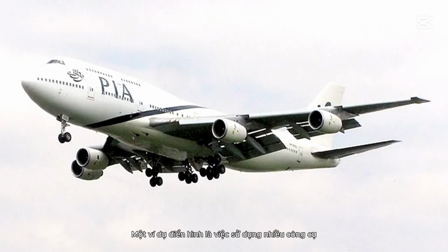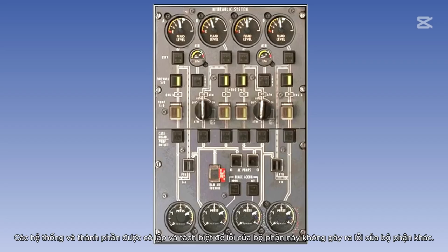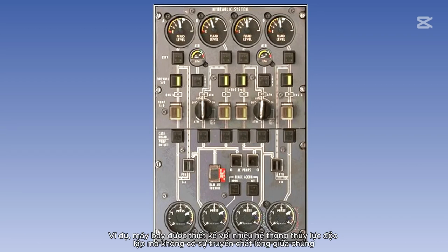A good example of this is the use of multiple engines. Systems and components are isolated and segregated so that failure of one does not cause failure of another. For instance, aeroplanes are designed with multiple independent hydraulic systems with no transfer of fluid between them.